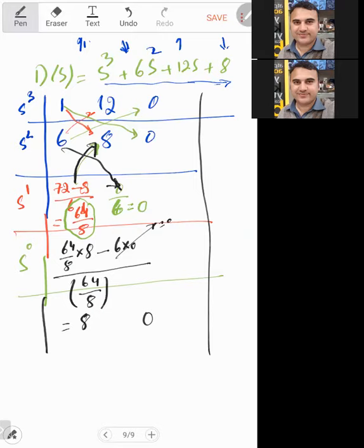In general, the Routh stability criterion states that the number of poles in the right half plane is equal to the number of sign changes in the first column of the Routh table. So we will look for all possible sign changes in the first column. If there is one sign change, we can say that one pole is lying in the right half plane and the system is unstable. If we have two sign changes, this means two poles are lying there, and so on. So the number of poles in the right half plane will be equal to the number of times the sign changes in the first column.